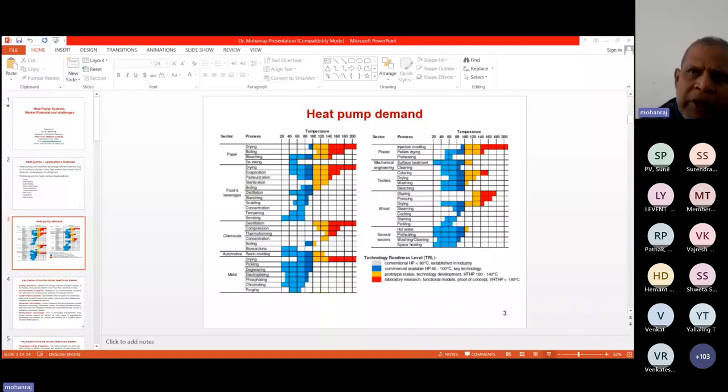In China, we have more standardized heat pumps available, even to meet requirements up to 120 degrees centigrade. But current research progress is being made to produce hot water at a temperature of around 150 degrees centigrade using some olefin refrigerants. So there is another problem: there is no proper working fluid to meet the heating demand up to a temperature of 150 degrees centigrade.